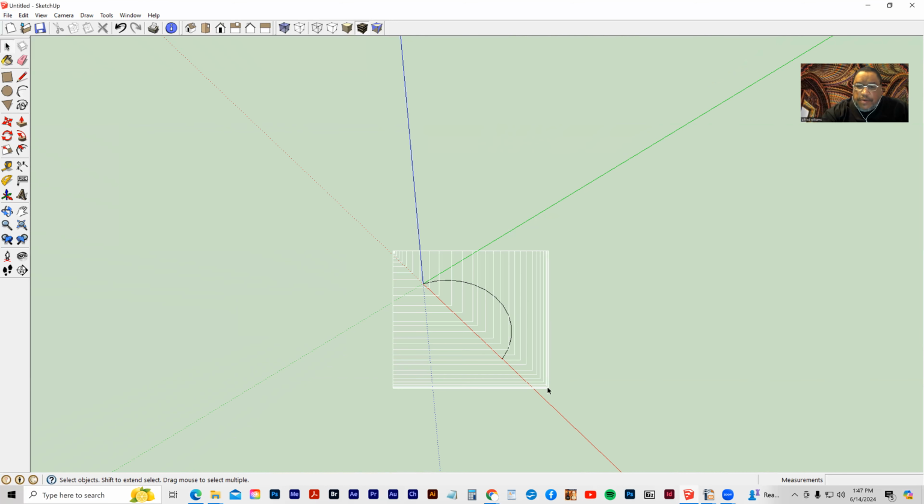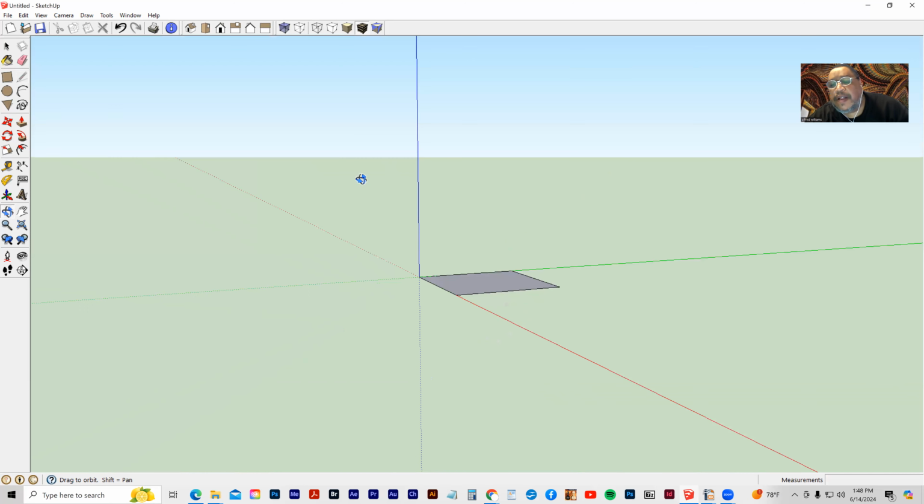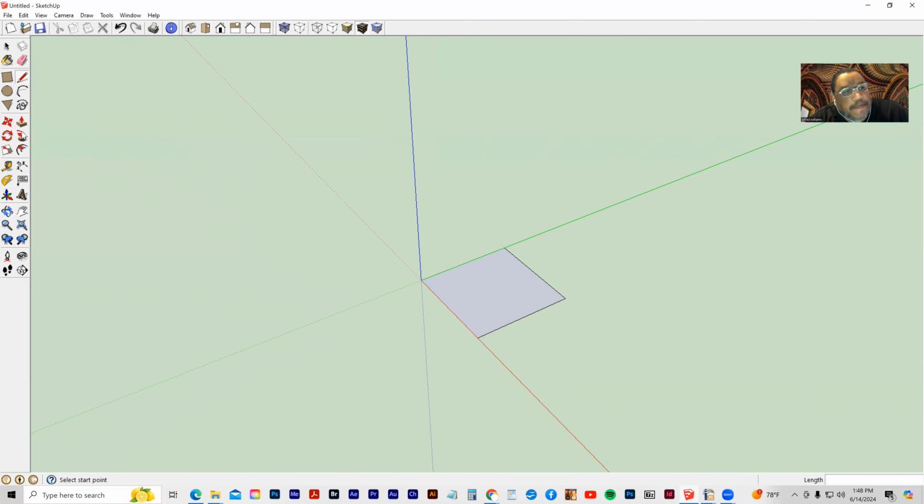And when you're using the pencil tool or the arc tool, I can freehand or I can set in a measurement. So if I wanted to make a box that was 5 feet by 5 feet, I'd click, start to drag out before I click again. I would type in 5'enter, and now I have a line that's 5 feet out, and then I'll move across here and type 5'enter, and then I'll come down back to here. That's going to be 5 feet. And then when I come back to here, that's going to be 5 feet. So I've made a box that's 5 by 5 feet.